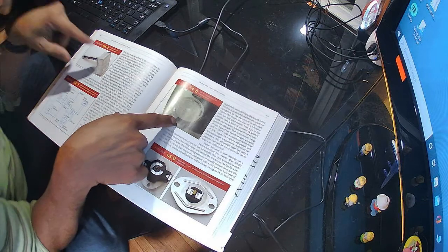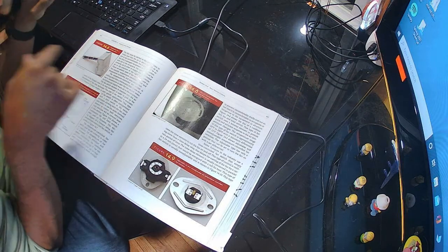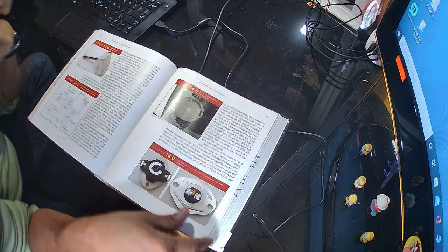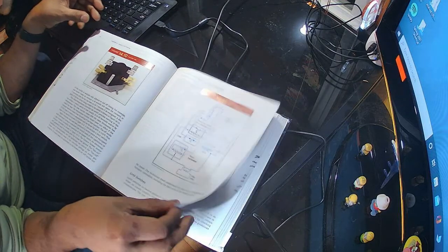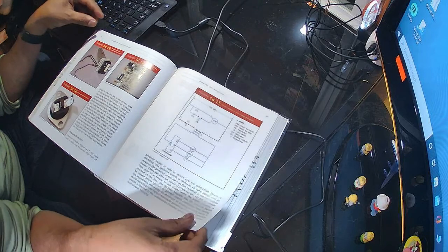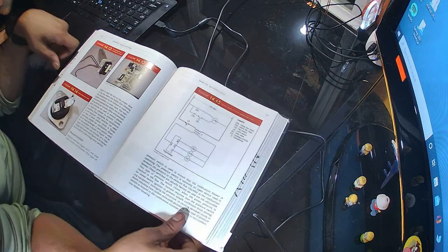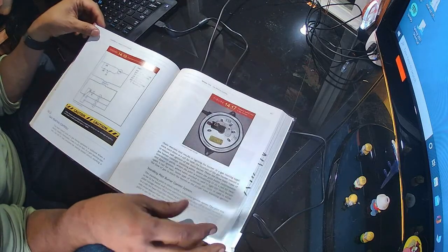So the function of these controls here, as it's illustrated, is to measure the temperature of the air passing through. And based on that, it will turn on or off a switch, which is a very good advantage to have when you have a hot air system. Some of them come with timers as well, as you can see here, and they operate a lot of fan motor switches.